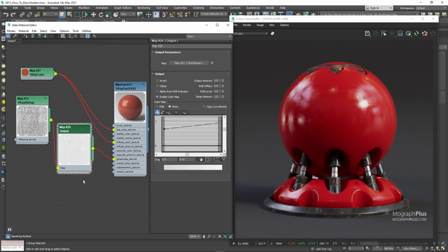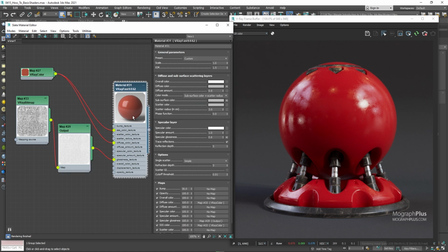Another thing that you can do to make your shader look more realistic is to make the perpendicular faces a bit sharper compared to the parallel faces to the viewing direction. If we were using a V-Ray material, we could have used the coat section there. Unfortunately, Fast SSS2 does not have a coat layer at the time being, so we might need to get our hands a bit dirty and do it manually.